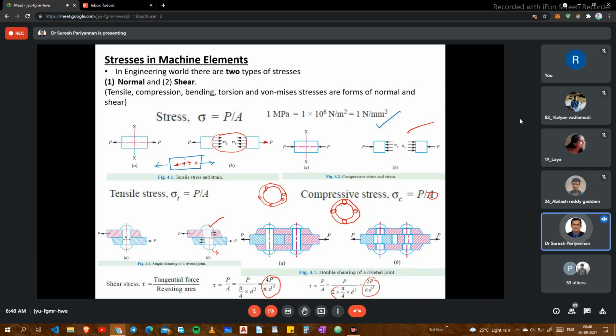The shearing force acting between the plates, the thin sheet or component, the same shearing stress will be acting on the rivet. Hence, we can avoid the shearing stress in the rivet as well as between the components, and hence we can avoid the failure. So that's what people are going for, more rivets.